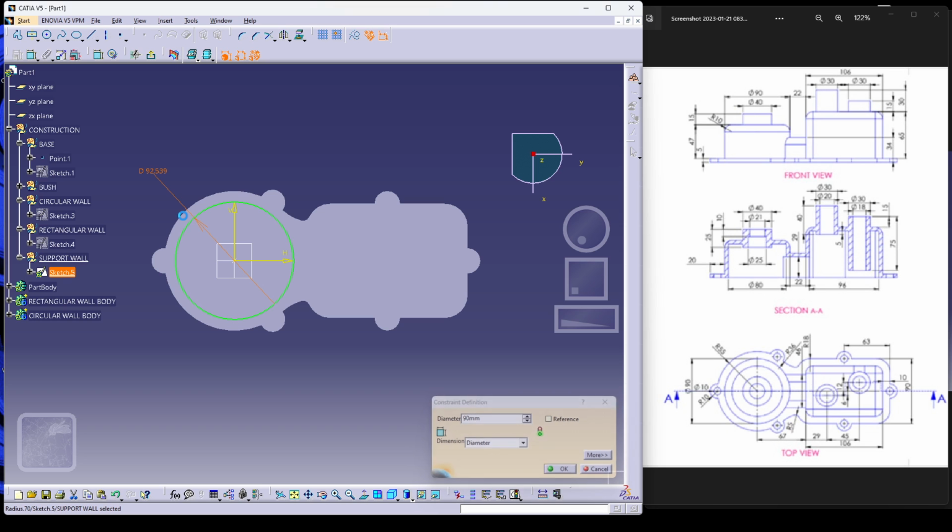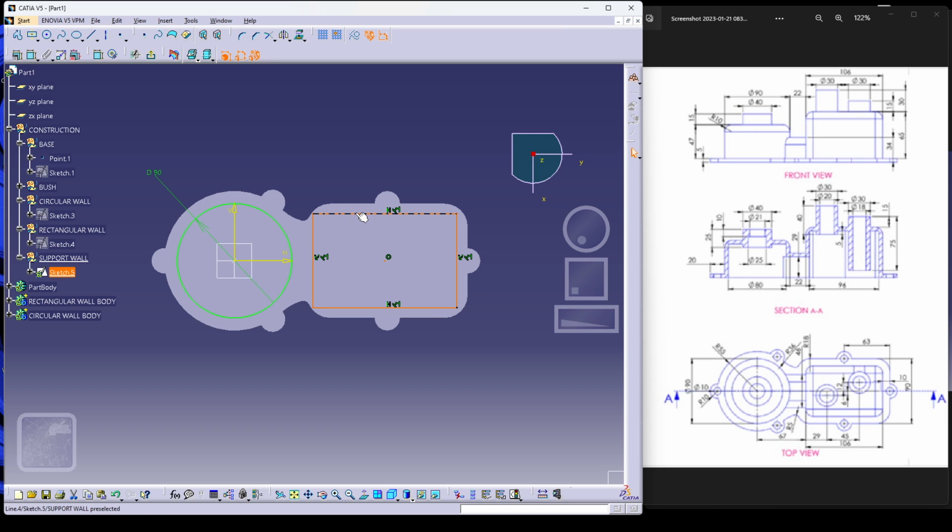Yeah, and then for another, this rectangle, we are going to select another rectangle over here and define this. Actually we don't need the rectangle, we just need a line, simple line. So let's draw a line over here and give it a difference from this point to be 67.